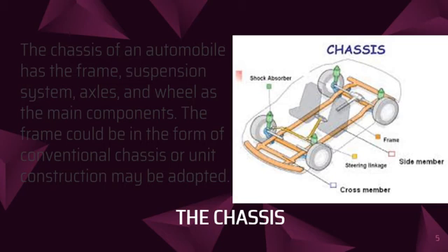The suspension system absorbs the vibrations due to up and down movements of the wheels. Springs and shock absorbers connecting the frame and the axle perform this function. The springs can be leaf spring, coil spring, or torsion bar. Even rubber or air can form the material of springs. The wheels of the vehicle can be suspended independently on springs or on spring-suspended axles.